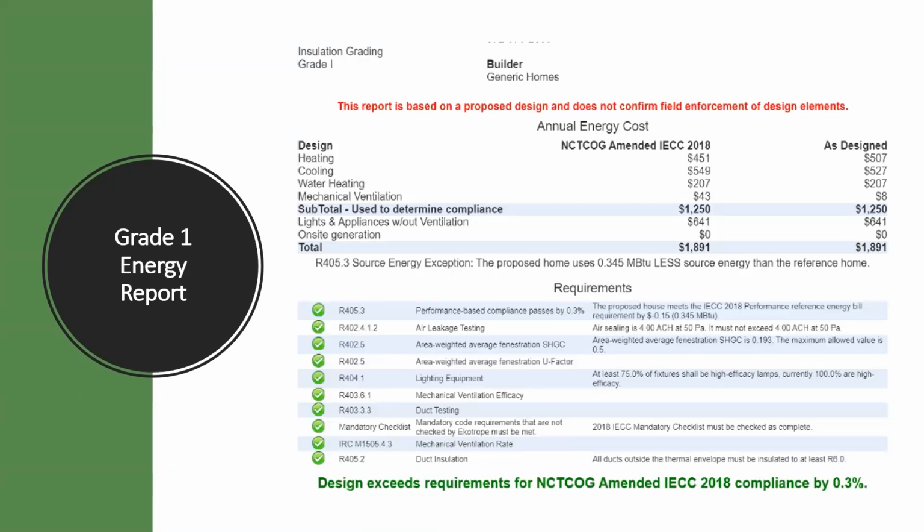The SHGC is equal. The mechanicals are equal. The only difference is that the grade of the insulation installation on the exterior wall and the attics are listed as grade 1, grade 2, and grade 3. All of them do have grade 1 attic insulation. The only thing I ask them to change is the wall insulation. So how much difference is it going to make when you have a poorly installed exterior wall?